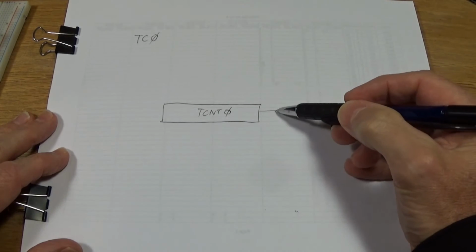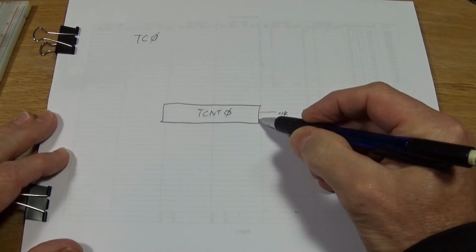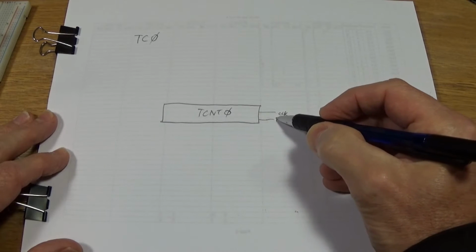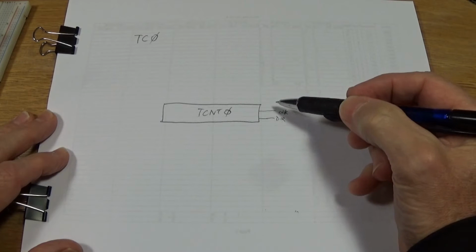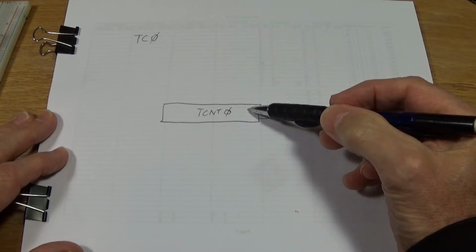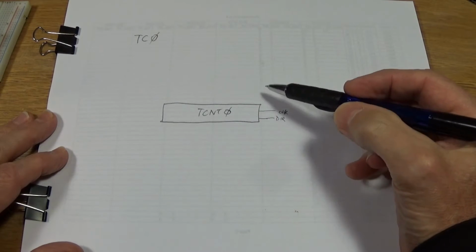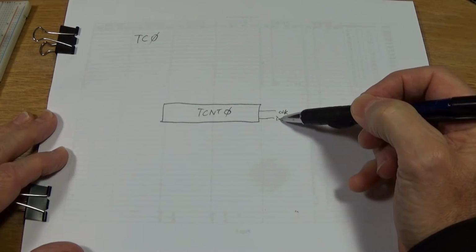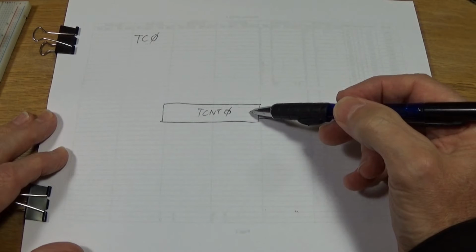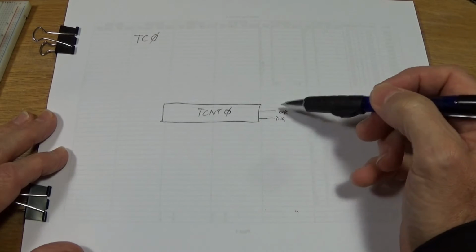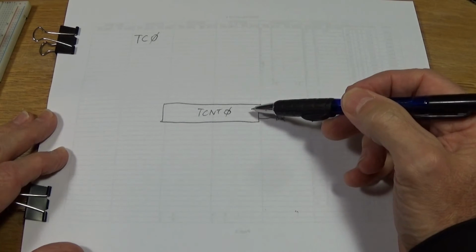There's another one called direction as well. And what the clock does is cause the register to change its value by 1, depending on the direction signal here. So you can increment the timer counter register by 1 every time it pulses the clock line, or you can decrement it as well.